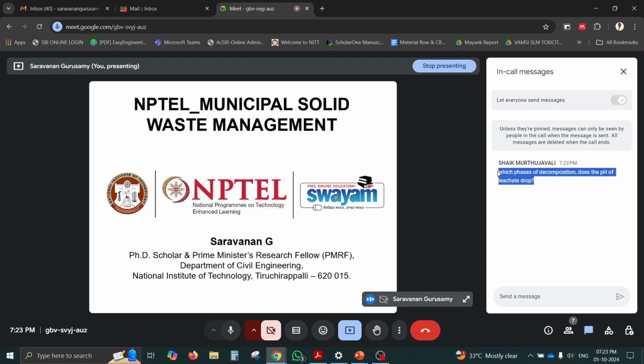I hope the question is not there in this week's assignment. I'll explain in the problem solving session. If you heard the whole lecture, you know there are five phases of gas generation mechanism and leachate generation mechanism. In the first phase, that is aerobic. The second phase, acidogenesis. Third phase, acetogenesis. So acidogenesis and acetogenesis are the two phases in which the pH of the leachate will be dropped.